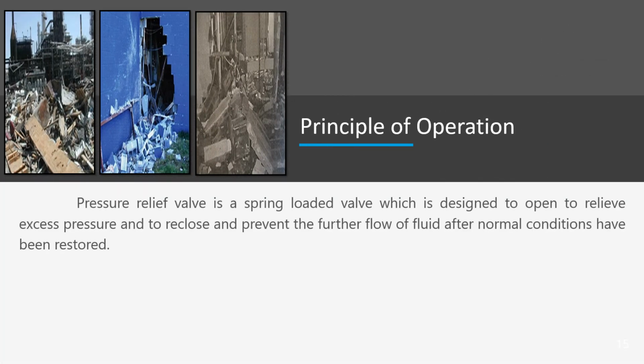Principle of operation. A pressure relief valve is a spring-loaded valve which is designed to open to relieve excess pressure and to reclose and prevent the further flow of fluid after normal conditions have been restored. It is characterized by a rapid opening pop action or by opening in a manner generally proportional to the increase in pressure over the opening pressure.